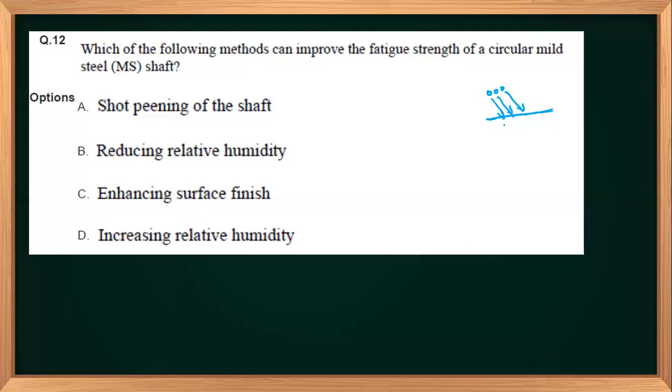Generally, your gears are toughened or hardened with shot peening techniques. Shafts can also be treated. In that way, the stresses it can take in the periphery will be quite high. So even though the cyclic loading will happen, your surface will still be hardened, still strong, which improves fatigue strength. Make sure this is done only for certain materials, because if a material is brittle in nature, it can create cracks and make it weak.